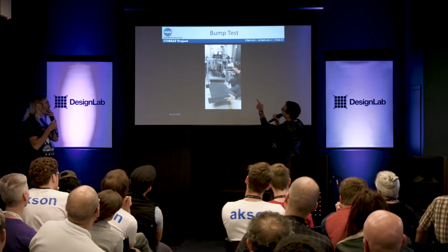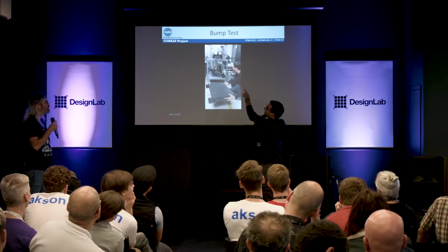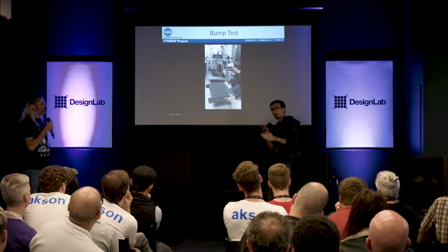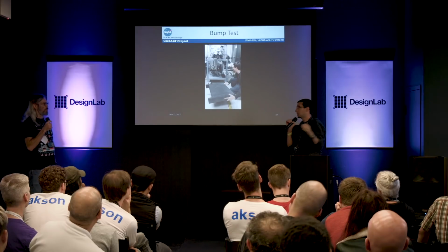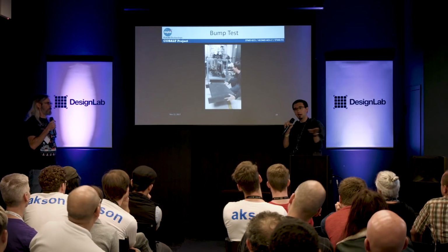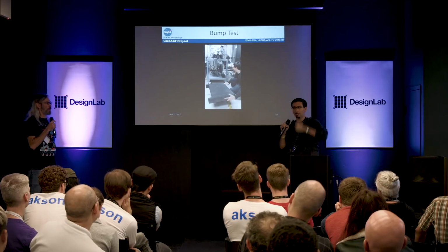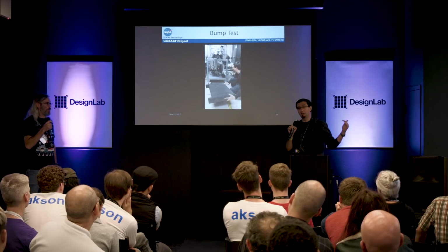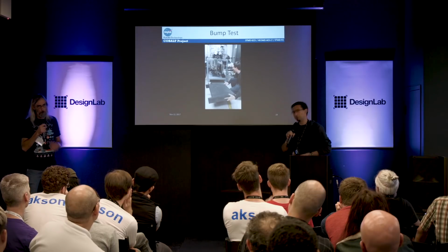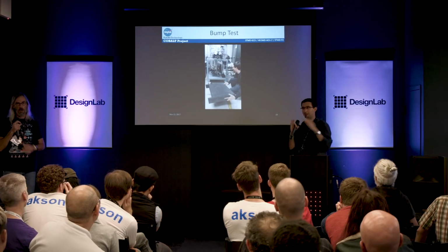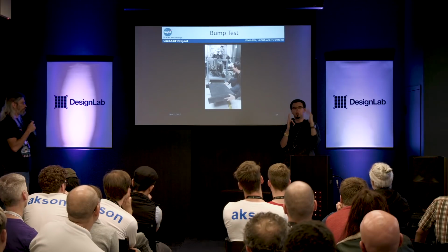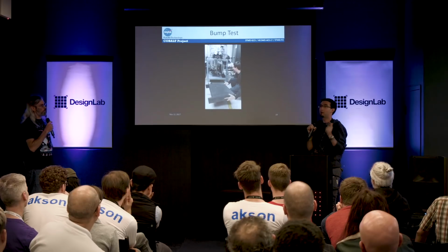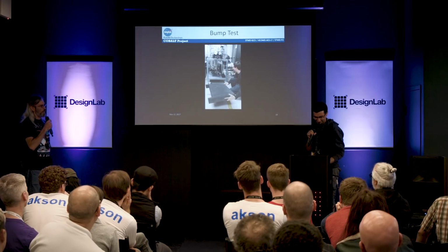So what's happening here is beam A, the beam in front, is actually looking at the surface here, and as you're dragging this piece of foam across, you see a velocity, right? As soon as it bashes into the cart, it comes to a stop, so velocity is high, then suddenly drops to 0. Meanwhile, the IMU is happy and dandy, and suddenly it goes, something smacked into me, and now you can get a nice little step function to compare your phasing. So it turns out a 99-cent piece of foam is way better than an expensive crane and swinging it around.